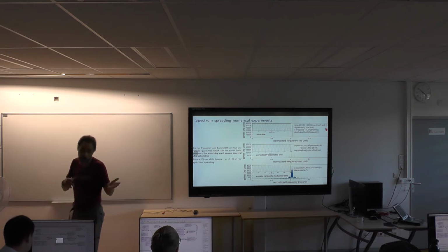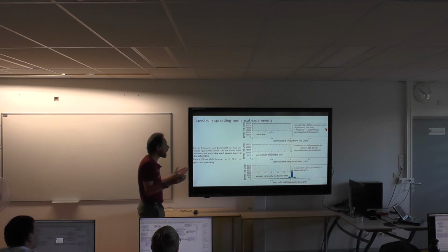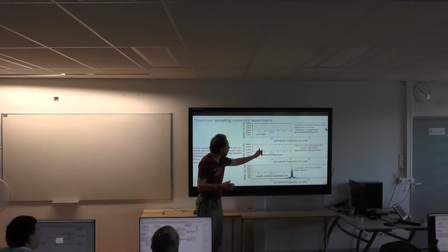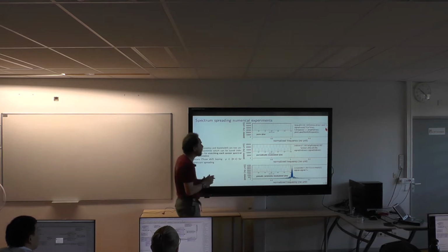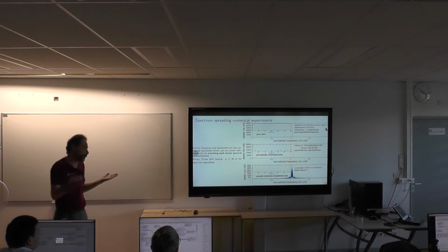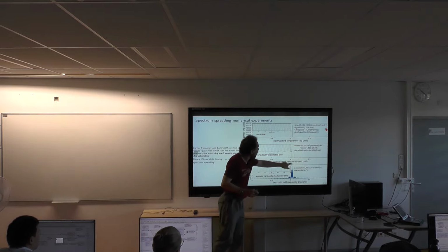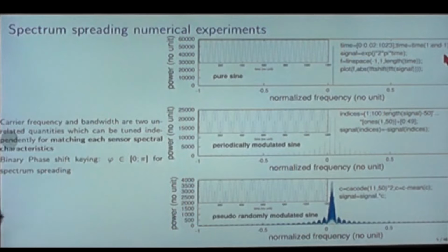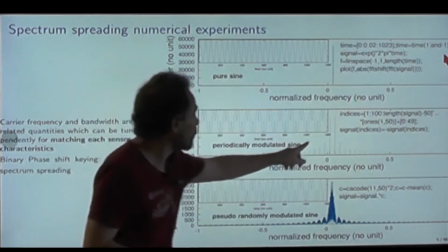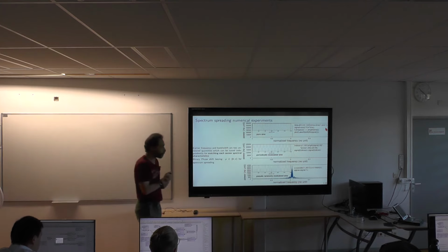So if earlier you had a 10 megahertz sine wave, 100 nanosecond period, now we can separate the first 100 nanoseconds from the second 100 nanoseconds. We have 200 nanosecond time resolution. That's a bit better, but still not very good. But what you see on the spectrum is now, instead of having just one Dirac spectral component, we have started spreading the spectrum. We've added more spectral components.